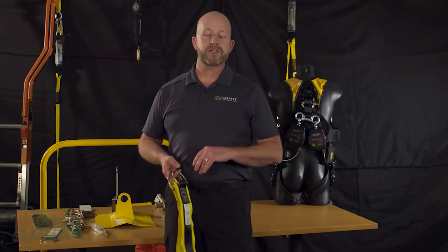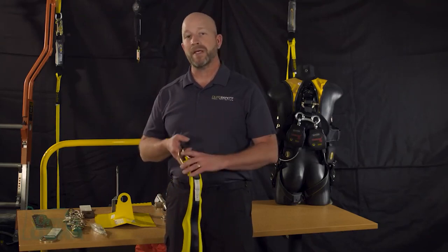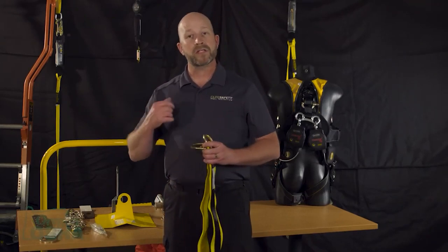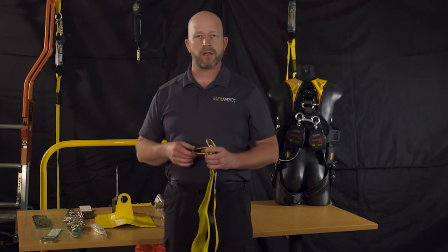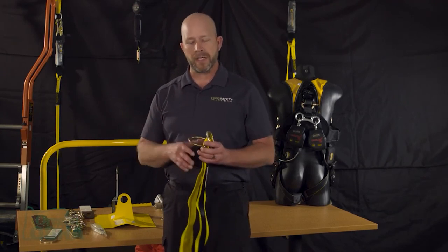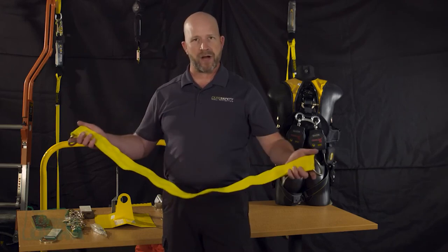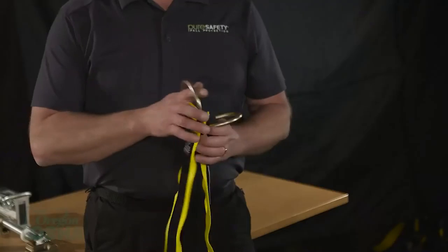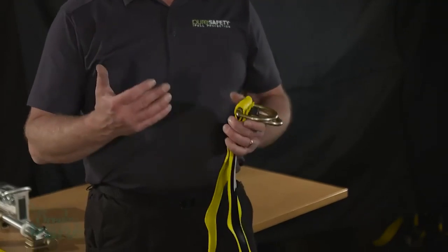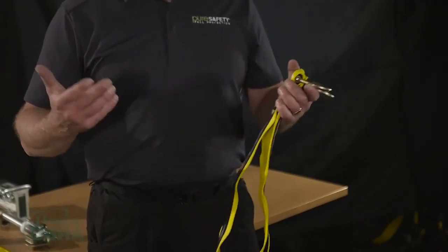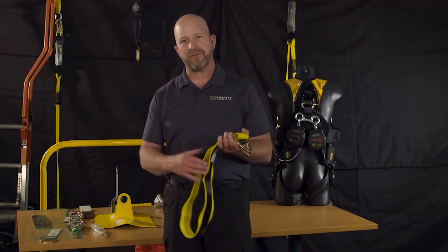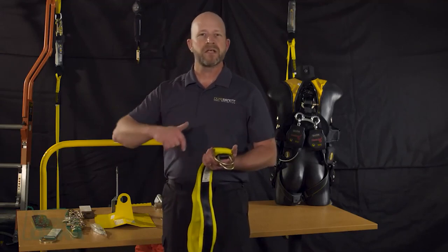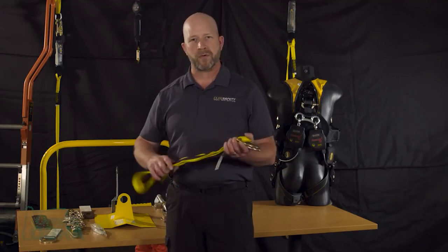Another very common one, especially when we talk about exposed I-beams, angle iron, or even exposed columns, concrete columns, partially or fully poured, is what's called an anchor strap. This is extremely useful, and they come in various lengths. Standard usually in the market is 3, 4, 6, 8, 10, 12, and 20 feet, but many manufacturers can even make them of custom lengths, depending on what we need to wrap this around.